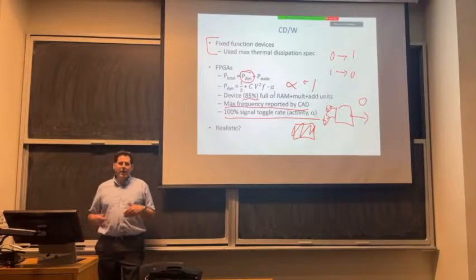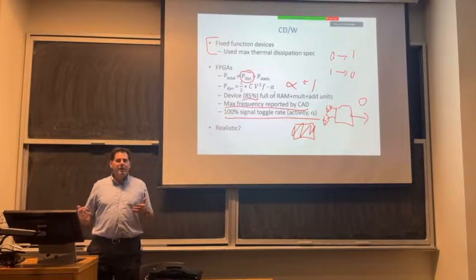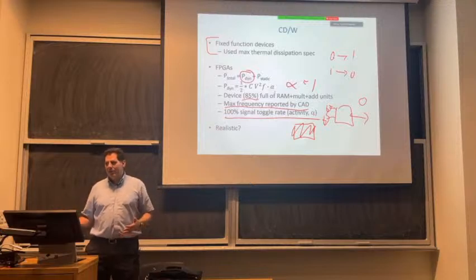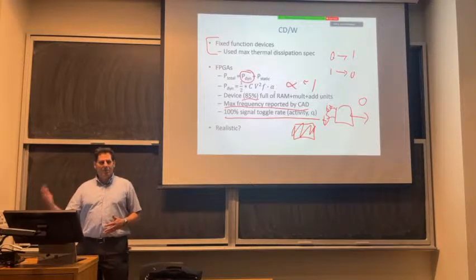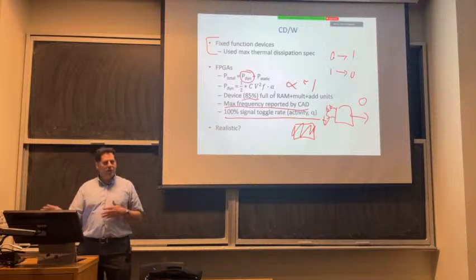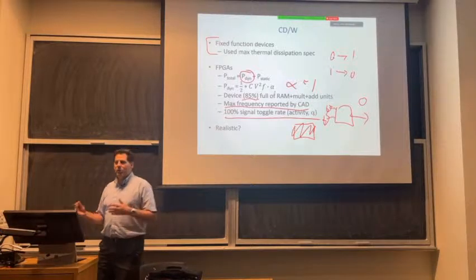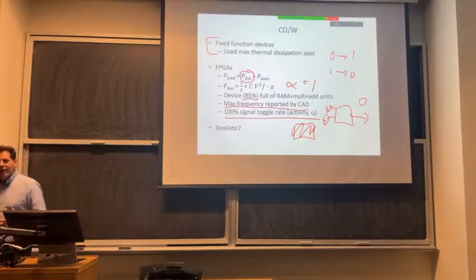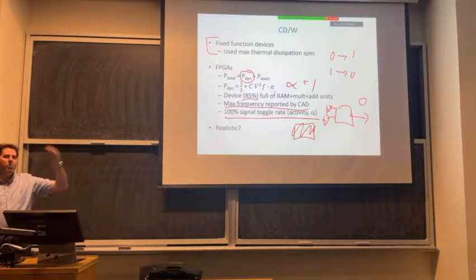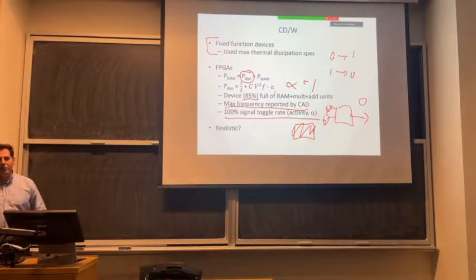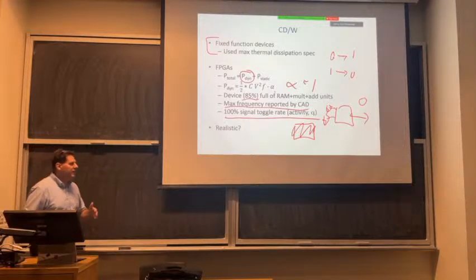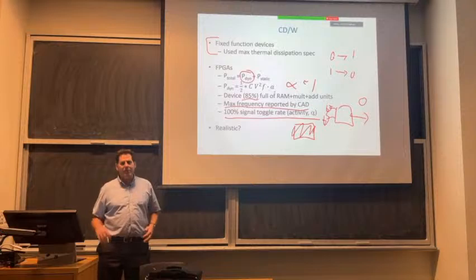Usually in a design, you actually get less than 50% because you have things like finite state machines, you have parts of your data path that might not be active, you have some correlation in your input data. There are a bunch of reasons why usually the toggle rate's less than 50%. Now, what they're doing, where they're taking a whole bunch of numbers from RAMs and sending them to multiply accumulate, could be 50%. Because you could say, well, every cycle, every compute unit gets new data. The new data has nothing in common with the old data because we're just doing a little kernel. So 50% is probably defensible here, but 100 is very pessimistic.